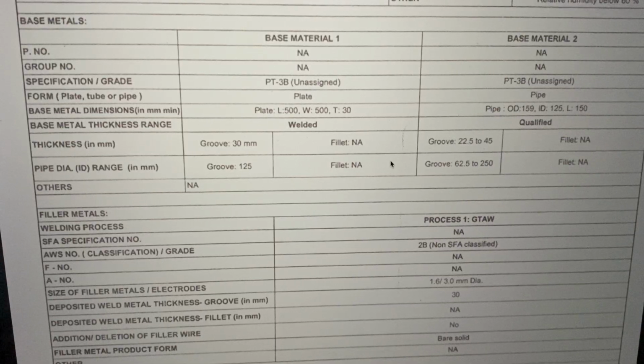We will be doing WPS PQR on this kind of smaller piece, but the equipment can be quite large, quite massive, quite heavy on heat extraction capability, and in that case, even though on a WPS plate a preheat of 50, 60, 70, 100 degrees may be good enough, and the interpass will be asking to monitor, in reality the preheat may be inadequate because of the mass, and the interpass temperature, because of the mass which is going to extract heat, will never be touched.